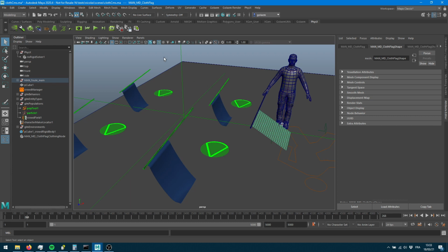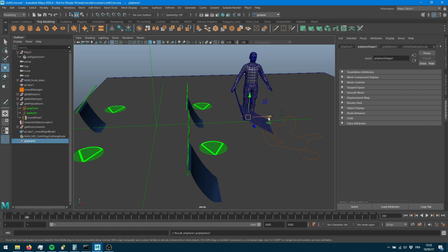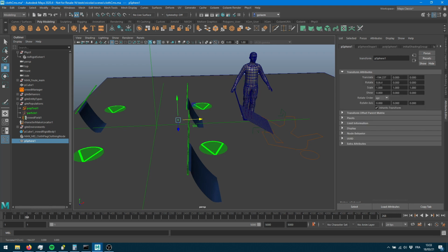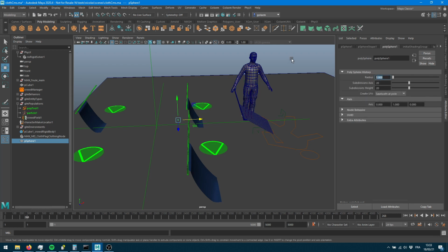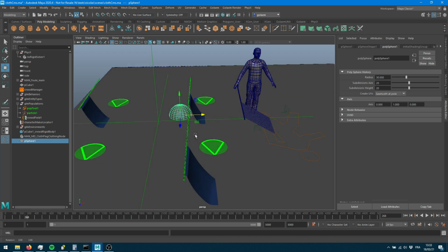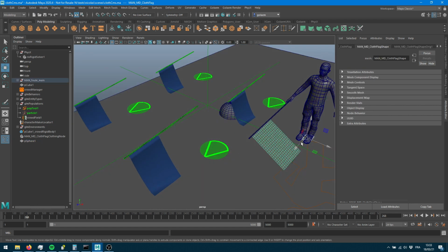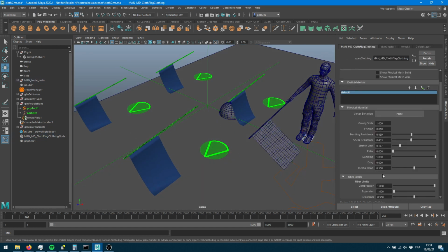Also, if you want to provide more colliders to your scene, make sure that you have really simplified shapes. You can have your own terrain, but use something different for the collision. Maybe let's say I want to have a collision sphere for that character here. I'm going to provide a radius of 100, so it's, well, maybe not 110. Maybe more. Let's do 30. Okay. And if I want this to be taken into account by my behavior, also let's go back to some regular damping here, so it doesn't take ages to simulate.